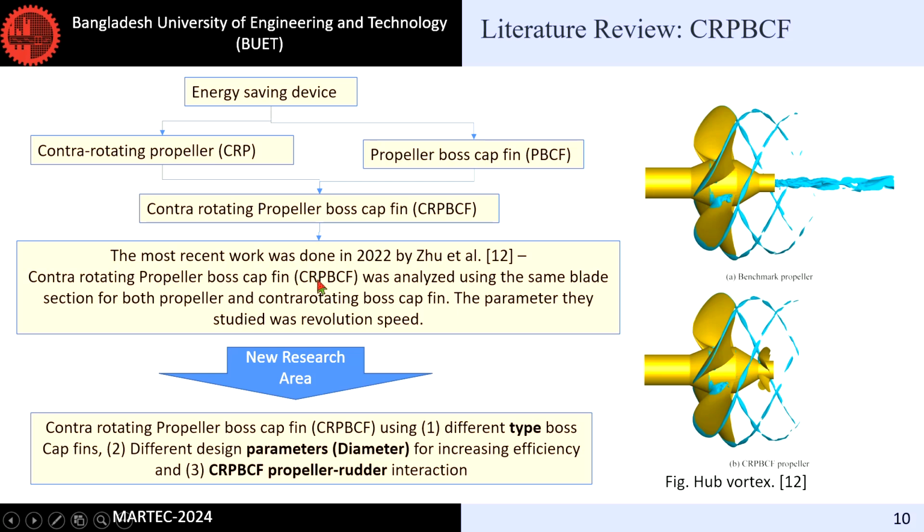They left the frontier at that point for us to explore, and we further pushed this boundary to explore different types of contrarotating boss cap fins and different parameters such as diameters, and then we attached the rudder to see the contrarotating propeller boss cap fin-rudder interaction.